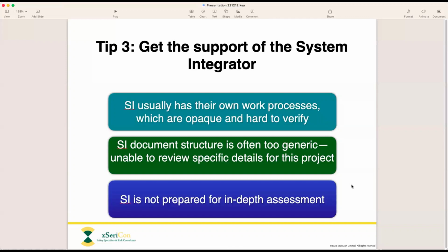For example, it can raise an alarm, or it can even trip immediately if that is appropriate in terms of what is needed to put the process into a safe state. So that behavior needs to be defined. And it needs to be specified that this is what the system is actually going to do.